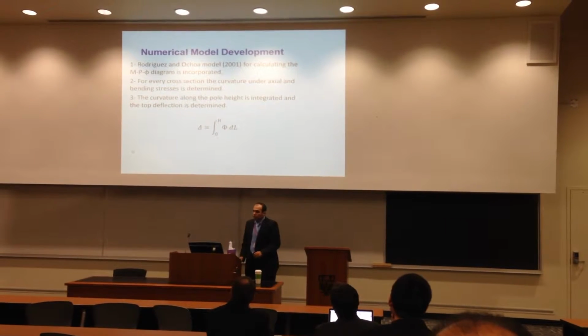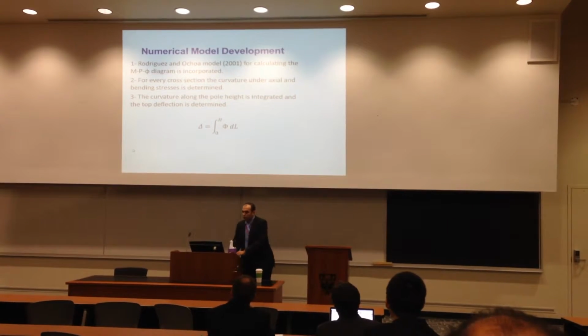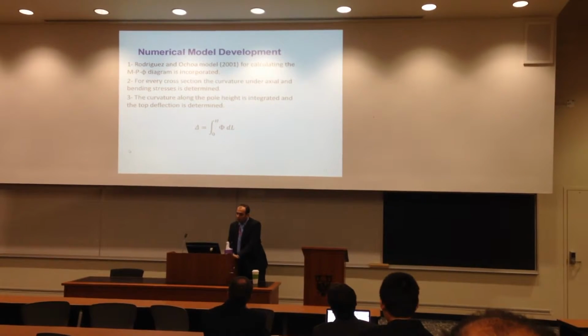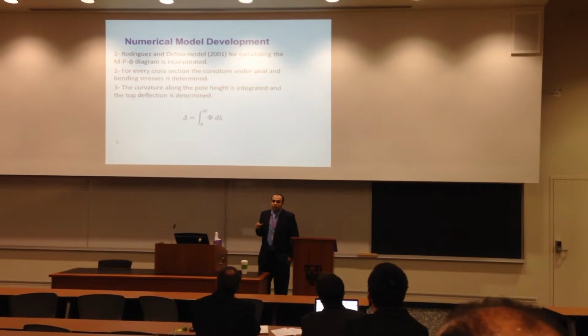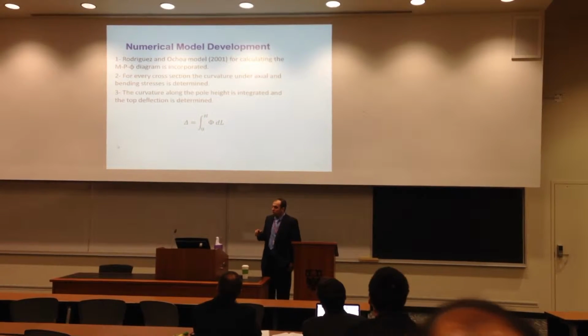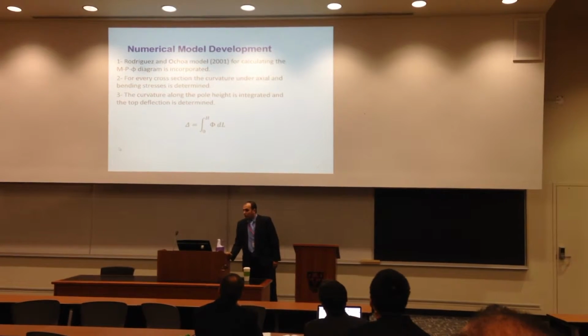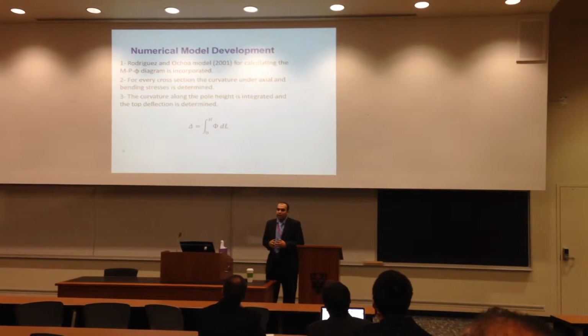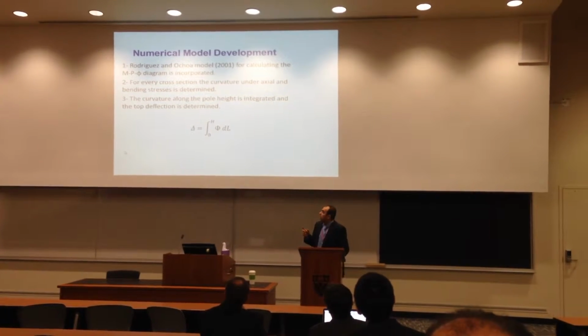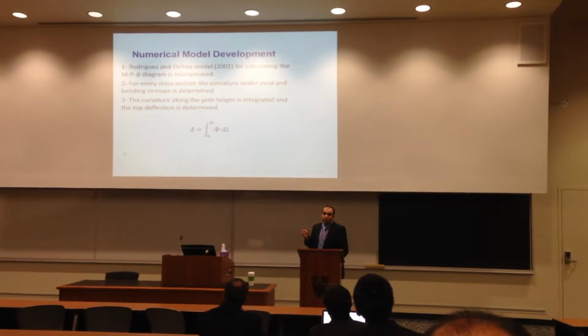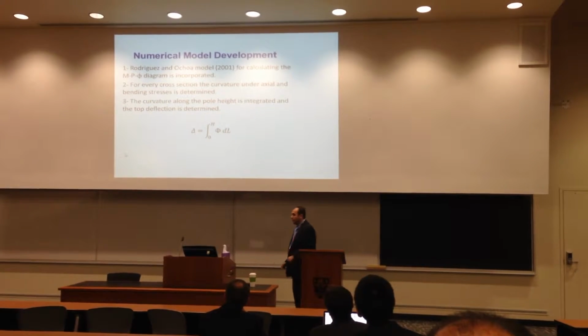During the development of the numerical model, the approach of Rodriguez and Bosco from 2001 for calculating the moment curvature diagram under specific compression forces is incorporated. For every cross-section, the curvature under axial and bending stresses is determined, and this curvature is integrated along the height of the pole to determine the top deflection.